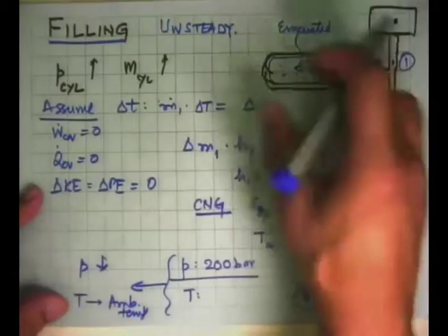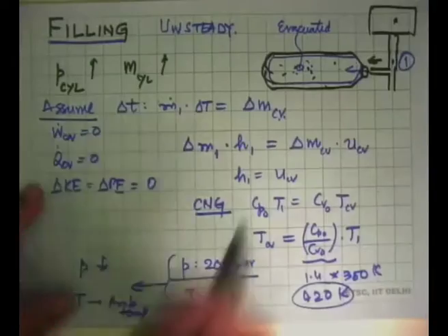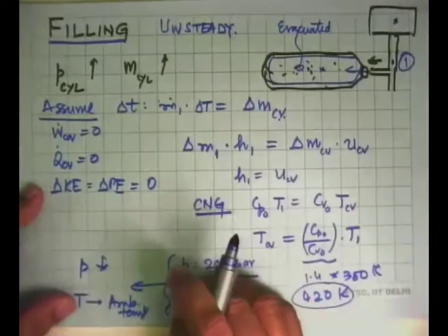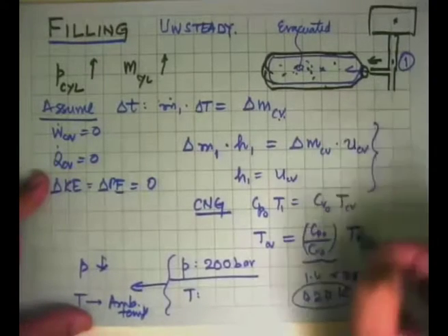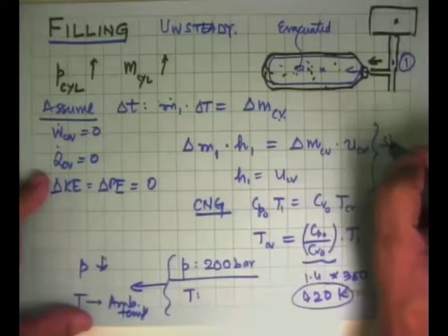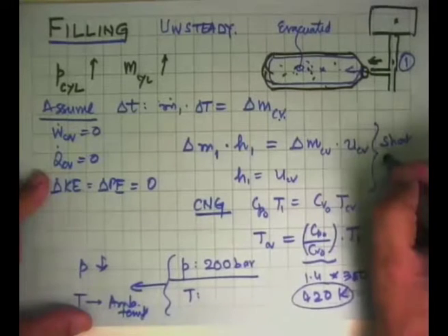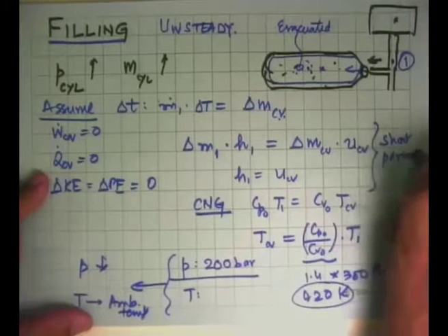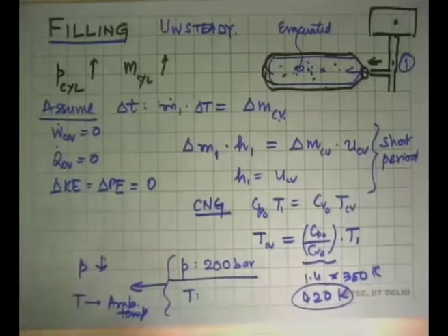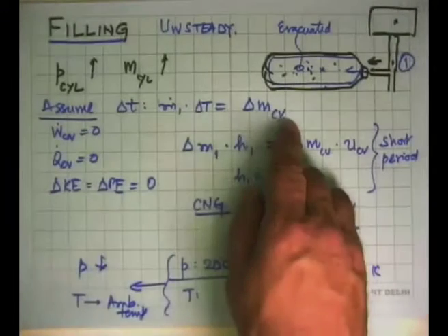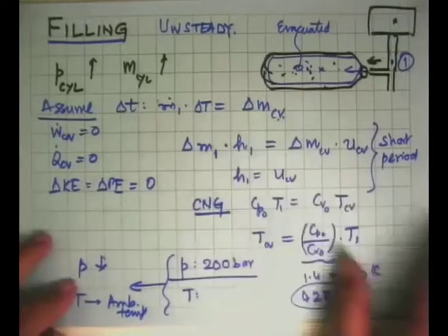And this is one set of problems that we tackle. The trouble is that since the state of the substance inside changes with time, one has to be very careful that when we apply this equation, it is only for short periods of time, and the mass that is put in is also of a very small, limited amount. Otherwise, technically, the type of integration that we did to get delta MCV cannot be done.